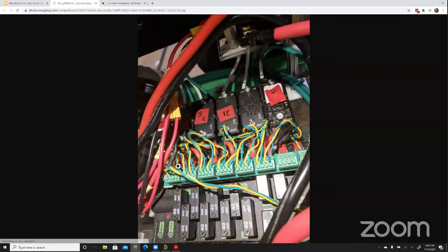There are some times where maybe you can make some wiring cleaner or easier to maintain. This is an example of something that I don't think gives us any kind of competitive edge necessarily, but it was a way that we could try to do something. So we made a custom PCB that had these spring cage clamps. And so our motor controllers could be plugged directly into here. We didn't need to use the Wago levers. We didn't need to solder it or do any other kind of connections between the motor controllers.